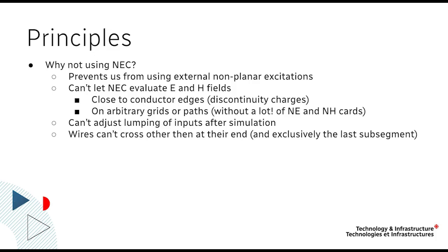So if you define a space like a tower, it has members, legs, diagonals, guy wires, and everything has to connect properly in order for NEC to work. That was really bugging because I'm typically going fast in things I do, and sometimes things overlap, and that's not good for NEC. So we developed our own factoring wire algorithm to solve this.